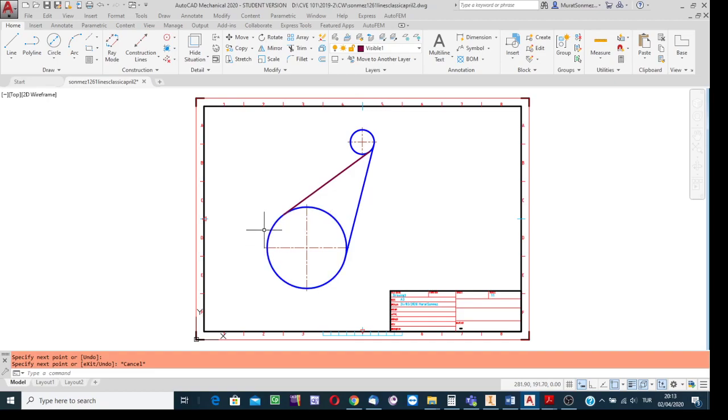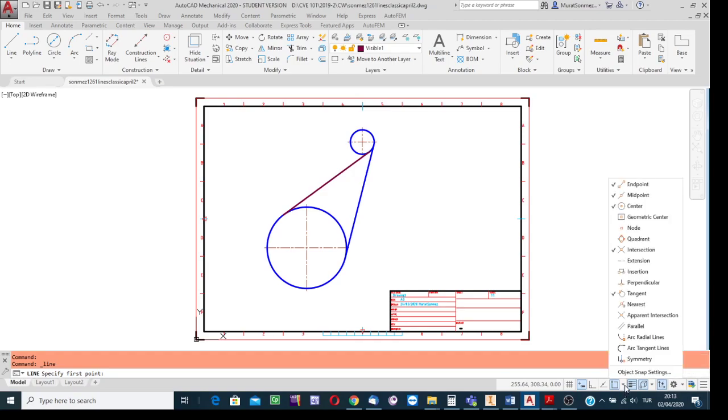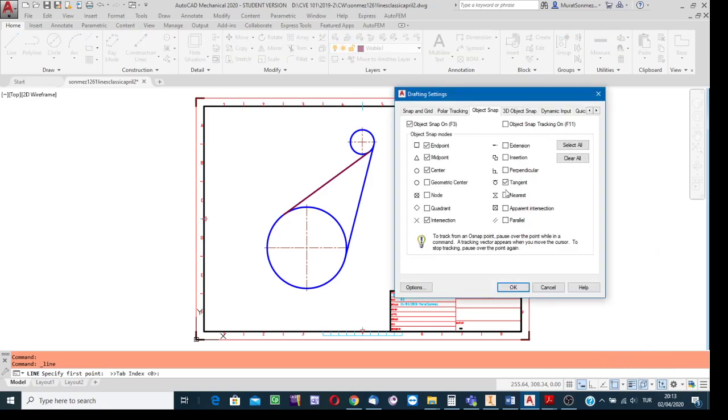Say that, similarly, a line is needed. It must be tangent to this circle, but it has only one tangent point. Okay. Start the line drawing process, and then the first trick: teach the software that the line is tangent. How? By changing the snap configuration. You know this. Click on this listing arrow and then select the snap settings option.